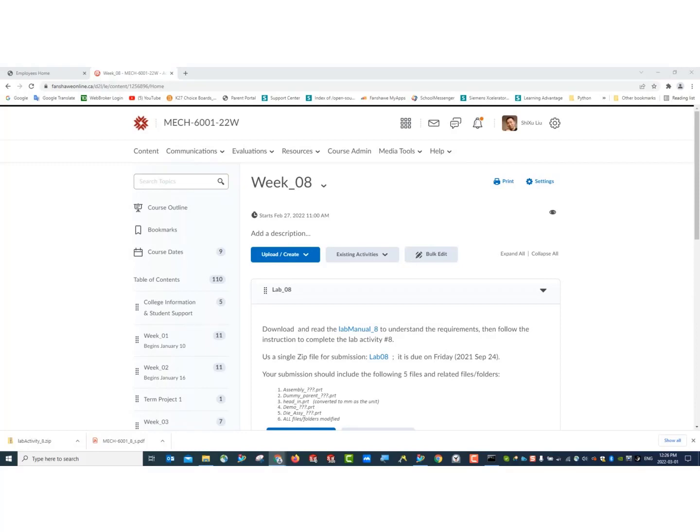Geometry link is another way. It allows you to make a copy of different geometry elements or feature elements from one part to another part at the assembly level. Once your original feature is changed, then the copied one with the geometry link will also update once it's opened again.